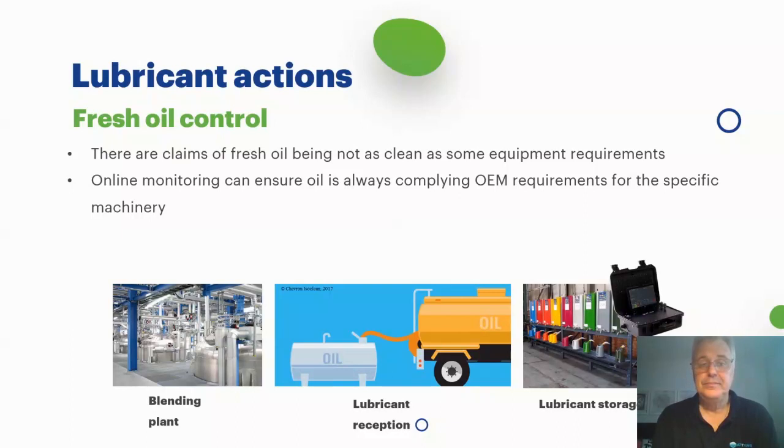Concerning storage, obviously we're not going to have a particle counter in each drum that is stored in the warehouse, but it could be interesting to have a portable particle counter at the warehouse where there could be IBCs or drums or storage tanks that could be suspect to contamination. So you may want to analyze them before you dispense it into the machine.